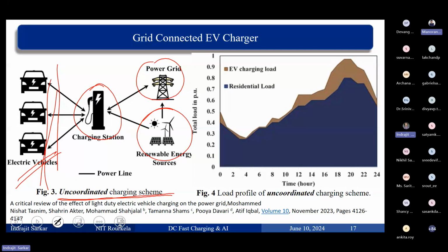When you are taking active power from the grid, it adversely affects the grid frequency. This statement is connected with the synchronous generators generating power at the generating station. If it is a coal based power plant, the coal is burning, producing steam, the steam is running the turbine, the turbine is coupled with the synchronous generator, and the synchronous generator rotor is eventually going to be affected.